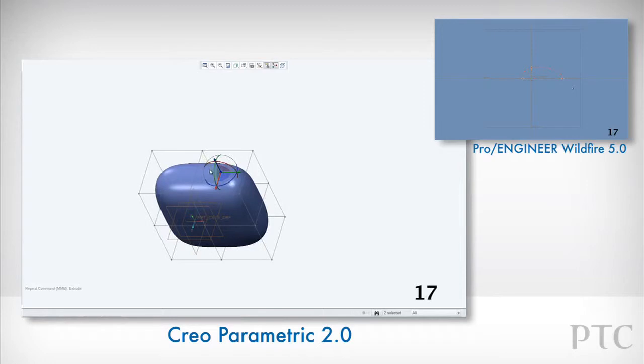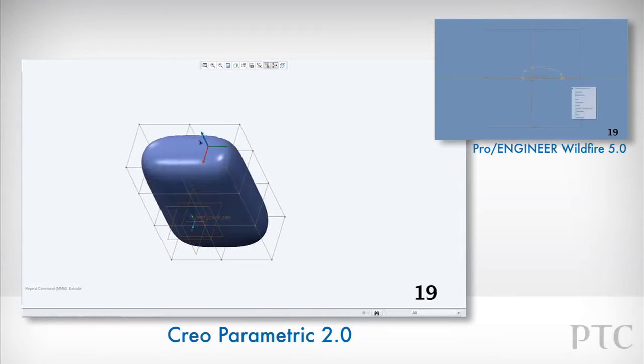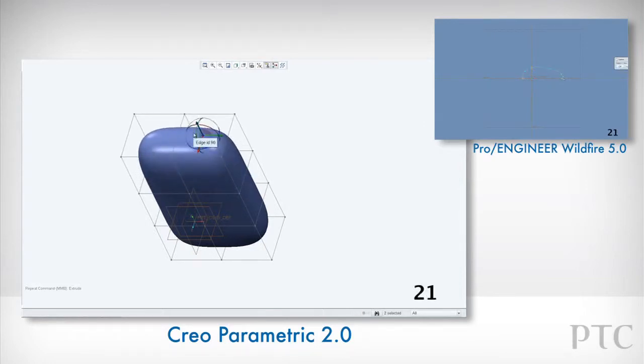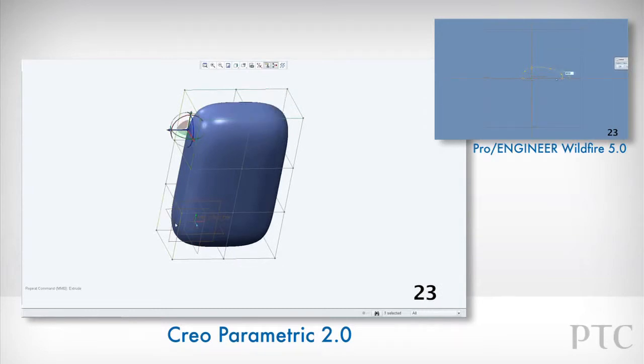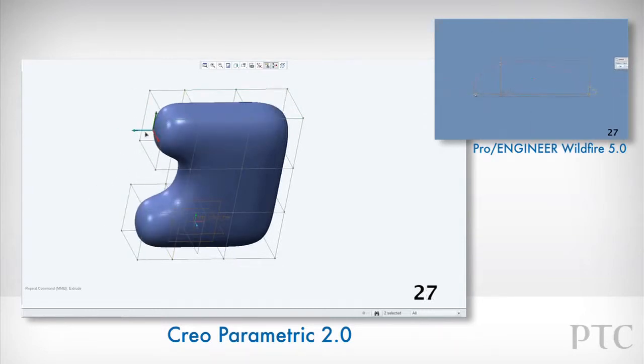In this case, we are going to extrude the faces of the shape using the commands available under the right mouse button. We can also extrude using the middle mouse button to copy the last command. The draggers used in Freestyle are consistent throughout the product, and using shortcuts such as holding the Alt key, we can also extrude faces easily. Using the Control key, we can select multiple areas on the control mesh and apply commands. Using the draggers, we can move or rotate the mesh as well.